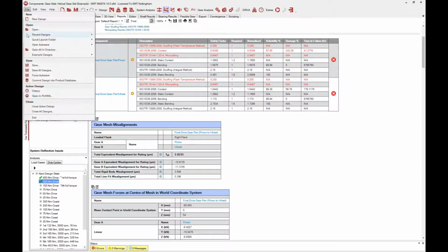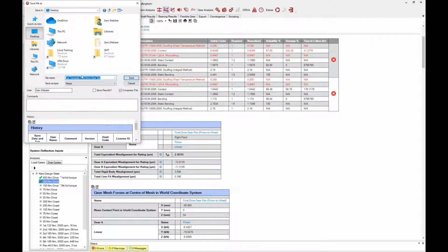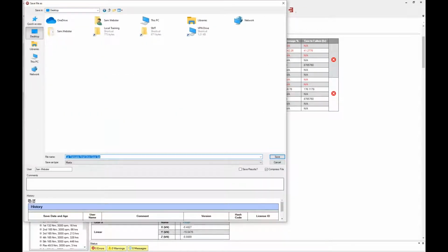However, in the actual save window, you'll see here that we have the ability to actually add to that report as well. So for one, we can specify the current user, and then we can specify some comments. So this is useful if you want to actually keep a running change log of what's going on in the model. So if you're looking for potential things that have changed between the last time you opened the model or changes that multiple users are doing to the model, you can put a comment in here every time you save.